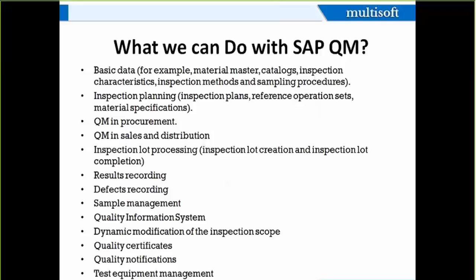Right. Now I'll jump to the next topic called inspection plan. The inspection plan is a kind of task list, and we can call it the way you want to do your inspection. So the inspection plan is a task list and processing tool. It defines which characteristics are to be inspected in each inspection operation and which equipment is to be used in the inspection. It is a systematically planned tool to make your inspection streamlined. So the inspection plan is very important master data for us.